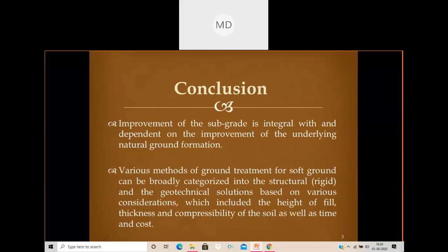So just now we studied about viaducts and piled embankments. So these are structural solutions. Generally, what we do for improving the ground surface, first we have to see if we can improve the soil quality or not. How can we improve the soil quality? Like by application of surface compaction, then preloading, vertical drains, dynamic compaction. These are the techniques where the ground surface is improved, the soil quality is improved, the shear strength is increased, bearing capacity is increased, pore pressure is reduced by various techniques.